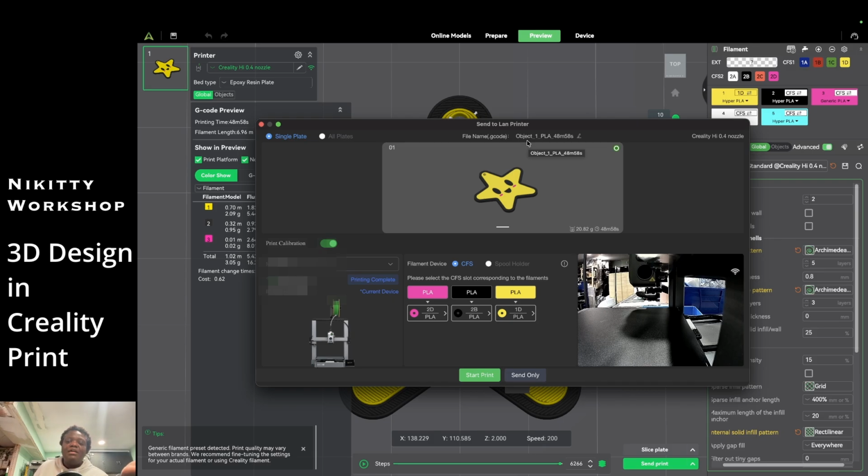But my mat was basically done because it wasn't calibrated. Something happened with one of the prints and it was off. So yes, I almost damaged my 3D printer by not calibrating. It is worth the wait. Calibrate before you print, please. Just a heads up from experience.